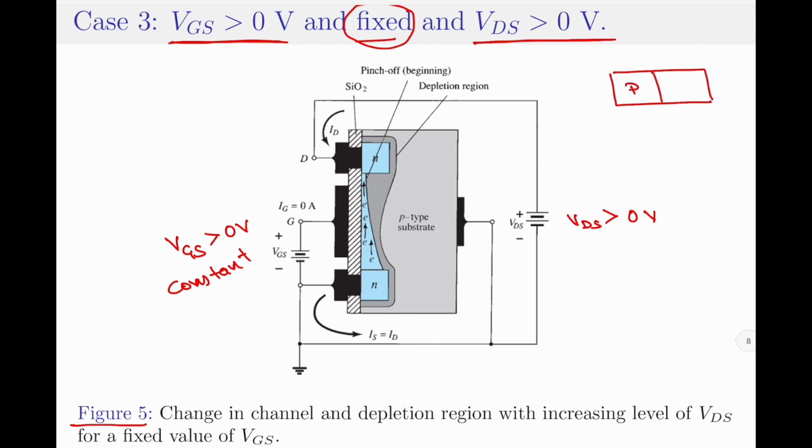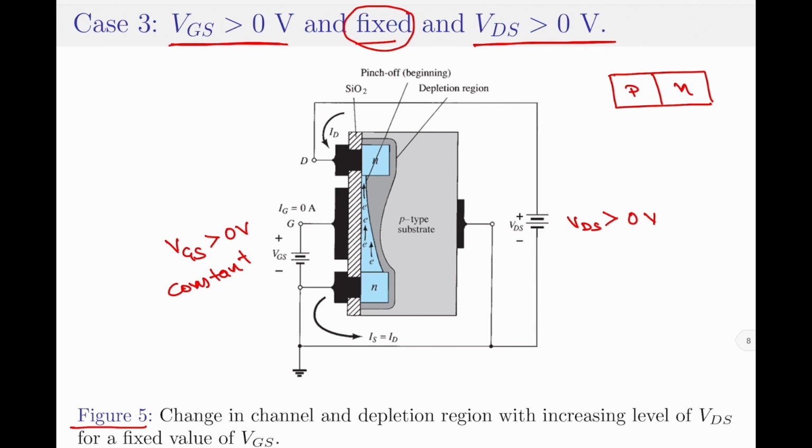Let me now reverse bias this PN junction by connecting a battery. So, the p-type semiconductor material is connected to the negative terminal of the battery, whereas the N-type semiconductor is connected to the positive terminal of the battery. Let us assume this is VA, which is the applied voltage.